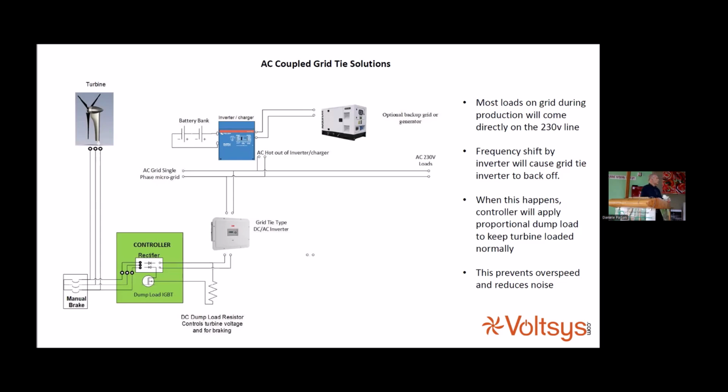Whereas if you use an AC coupled system, the turbine, the PMG, you have the advantage of it being completely a variable speed turbine that can operate at any speed, and you can extract power at whatever speed it is. But you can put that into an AC microgrid that's fed by a Victron or an SMA on the island. And so we have this system then that if this throws out a change to the frequency in the grid, we get to read that in our controller, and we vary the power accordingly.